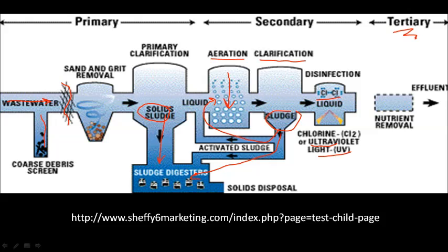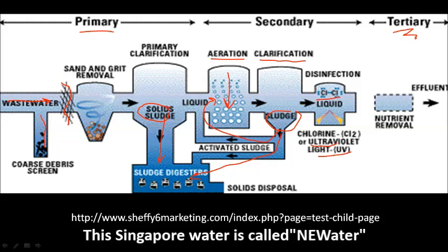So the water is collected from natural sources and is usually purified using alum, which is a chemical flocculant that will aggregate sediment that's contained within the water, and then the water is usually disinfected with UV light or ozone in pretty much the same way that we discussed before, and then depending on where you live, that water is usually fluorinated. I don't think anyone anywhere in the world directly converts sewage or wastewater into drinking water in the same facility, except I think Singapore has a plant that does that, I was reading about.